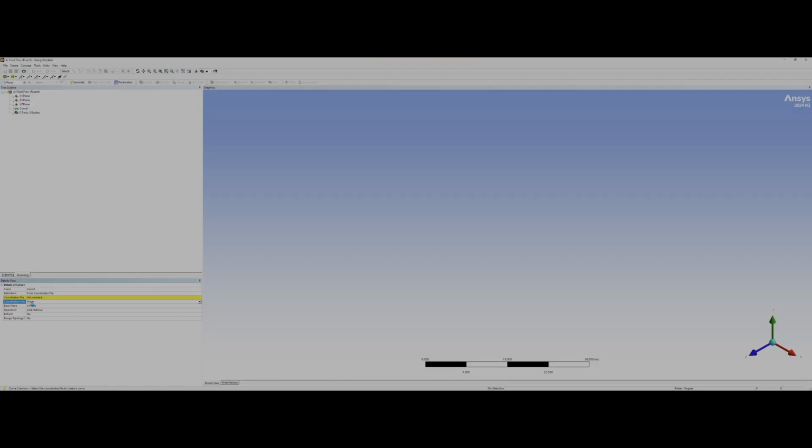Here in ANSYS, keep in mind our units are in millimeters, so we go to millimeters. And then in the corner file, you just look it up. I have several files here, as you can see, but we're gonna go here in downloads, and this is the exact same one that I've made. It works. Good. You could press F7 to zoom to fit. There you go. And now we make a surface from edges. Click on the edge, apply, generate. And there you go.